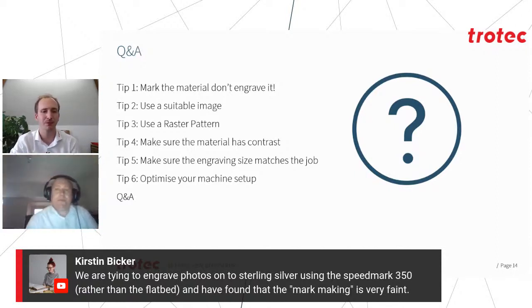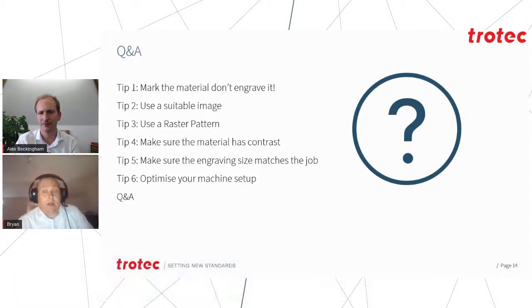If you've managed to cut down that image data enough, and again I'd refer back to something like Pencil Sketch, then you've got the ability to hit your substrate harder with the laser to go deeper and create more contrast, because you're putting less dots down. You can make each of those dots a bit deeper. So hopefully that will help.